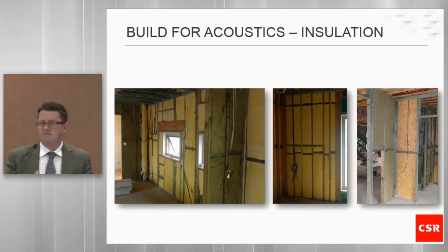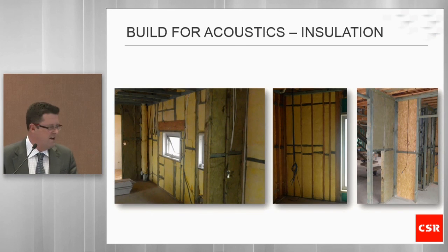How do we do this? Very, very pragmatically, very, very simple. We make sure that our insulation is fitted tight between the studs. We make sure that it's installed properly, because we know now that we're going to get better thermal performance. We're also going to get better acoustic performance, and we have less transfer of air through those gaps.